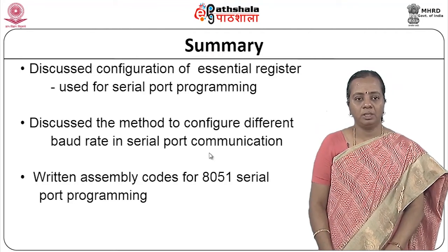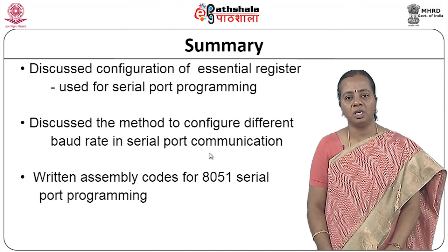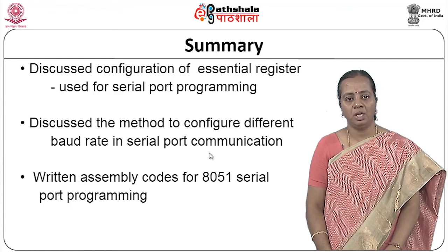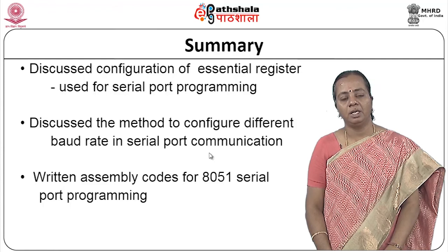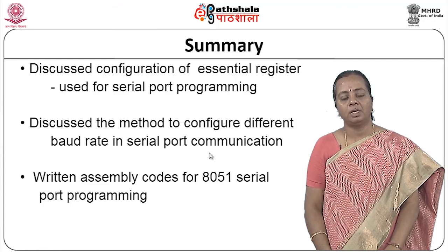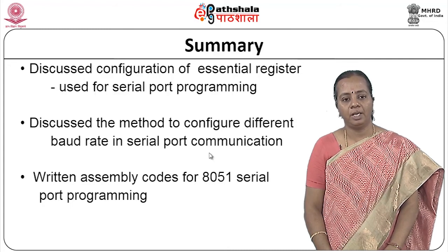So in this lecture we have covered how to configure the essential register for serial port programming, that means configuring the SCON register, and how we calculate the values to be placed in the timer for setting up different baud rates.